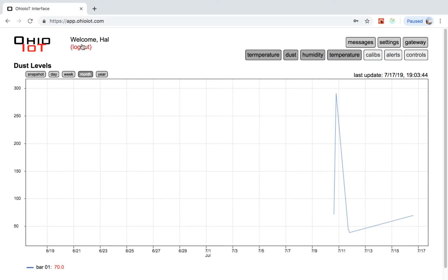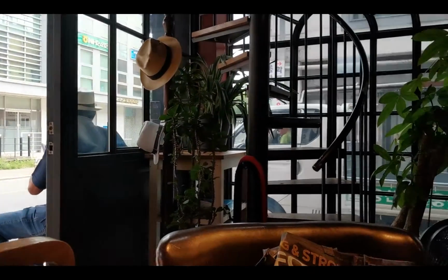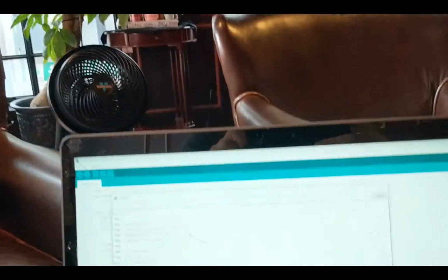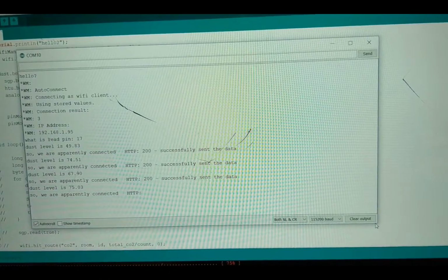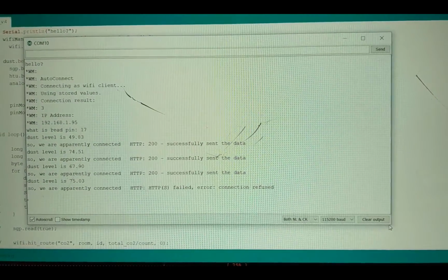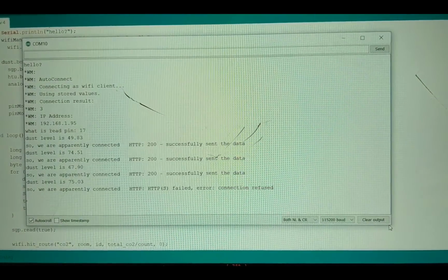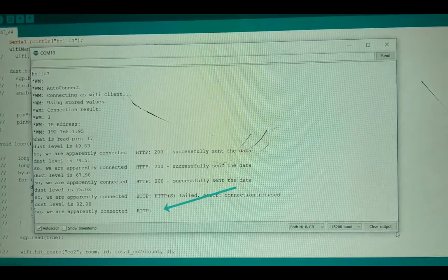I went to Burn and attached my laptop to the dust sensor I had installed there, and I wanted to monitor the serial port. And you're going to see a pattern here that I've seen several times before. The first web hit fails, and it resolves that failure and continues on and gets another data point, but you see the second time it just hangs up completely. When this happens, it doesn't recover.